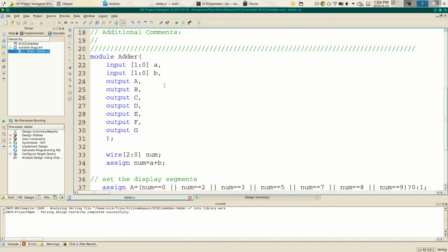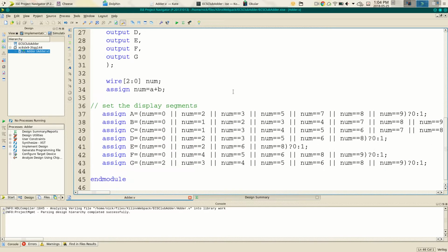And in 250, we have another chip, it's called a 7447, that would take these 3 bits and use it to drive these 7 segments. Well, I didn't have room on the circuit board I used for a 7447, so I made one ourselves. So basically, if your number is 0 or 2 or 3 or 5 or 7 or 8 or 9, then I want to turn on the segment A. And if it's 0, 1, 2, 3, 4, 7, 8, or 9, I want to turn on segment B. I sat down on a piece of paper with these 7 segments and just figured out which things to turn on for each digit you want to display.